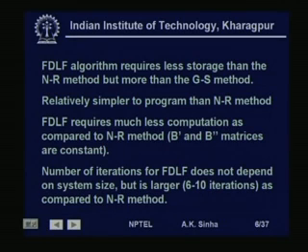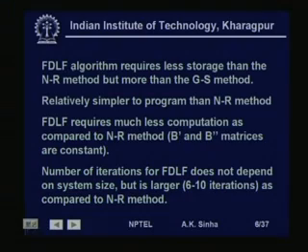A variation of the decoupled method, which we call the fast decoupled method, is very much in use, because it requires much less storage than the Newton-Raphson method. Actually, since we have decoupled the real power and the reactive power equations, that is, the real power P-delta equations and the QV equations.